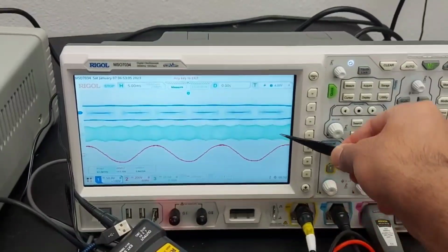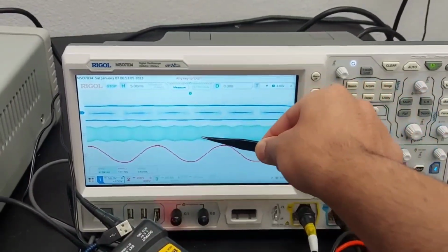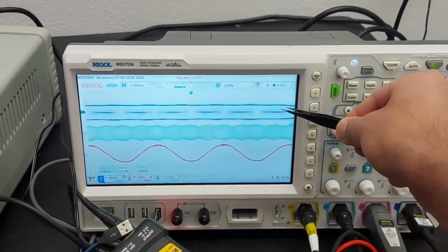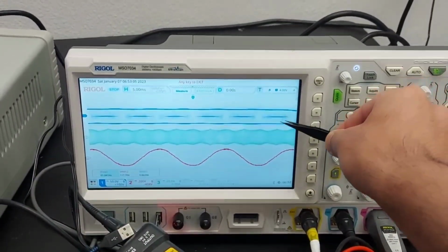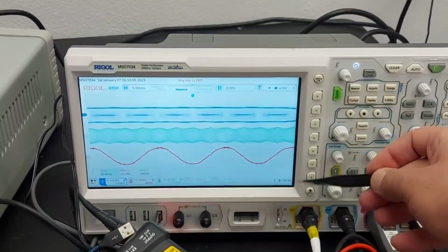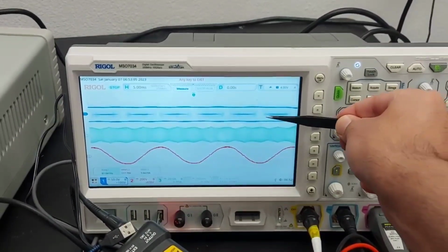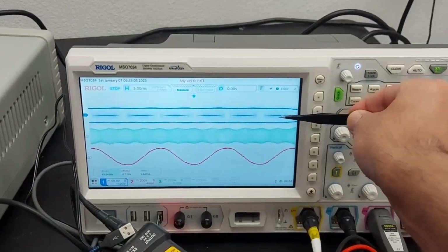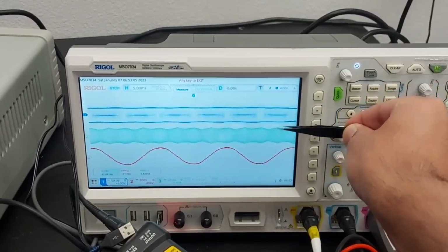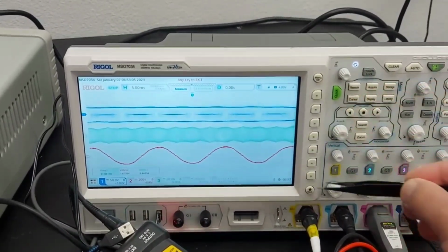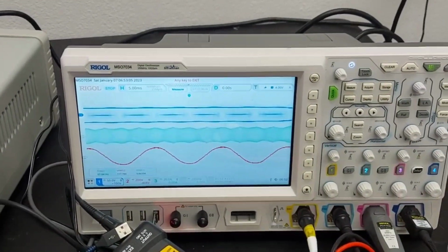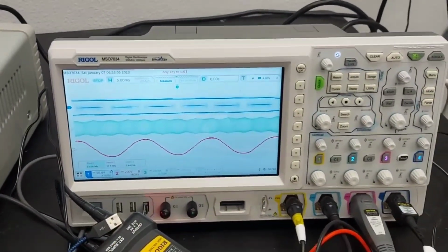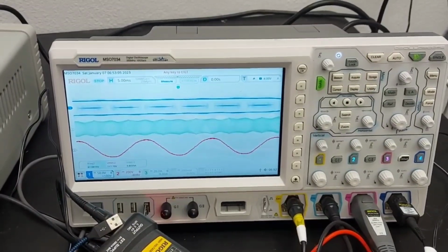Here you see the current through the transformer windings, and you can see that the voltage at the primary of the transformer is like this, which basically means that delta 1 is activated because we have these blue regions here. That means in these regions we have delta 1 activated. So as you can see, we have generated a pure sine wave with the aforementioned design and the aforementioned criteria that I have described in those slides.